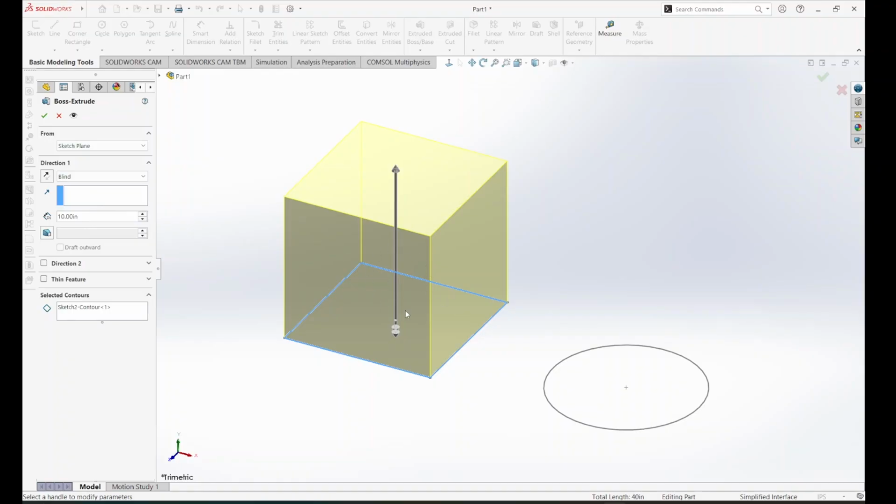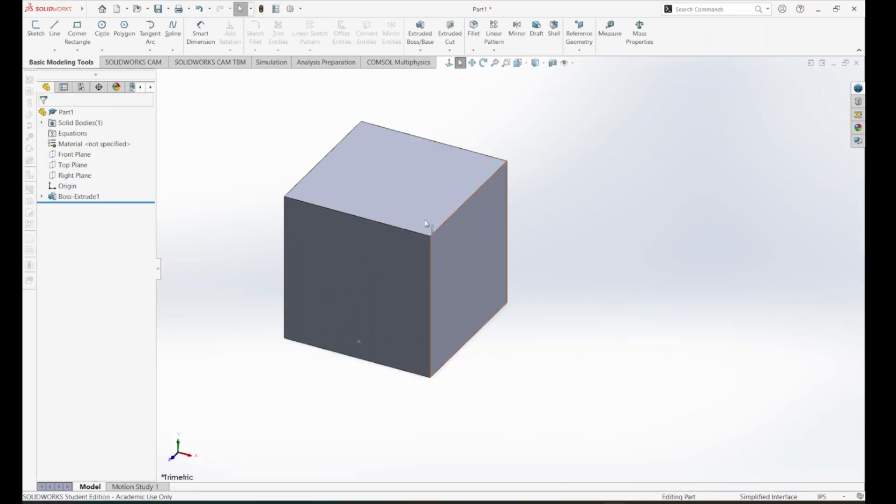From there, we can just click out, and you can see now it's previewing what it would look like. And go ahead and click accept. And now it's solid. So notice that now my sketches disappeared. So the way that we're able to get that back is our sketch actually became a child object of our boss extrude. That means if I hover right here, we are able to see that my two sketches are still here. But because I have extruded one of them, they all now disappear.